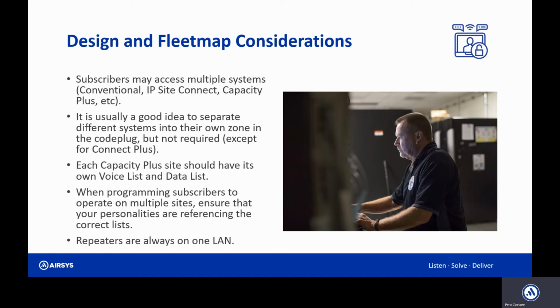because if you end up with a channel zone with loads of different systems that you can select with the channel selector, chances are you might call the wrong system or the wrong customer. So each Capacity Plus site should have its own voice list and data list. And again, you need to make sure that you reference the correct voice list in the subscriber code plug. And when programming subscribers on multiple sites, ensure that your personalities reference the correct lists.